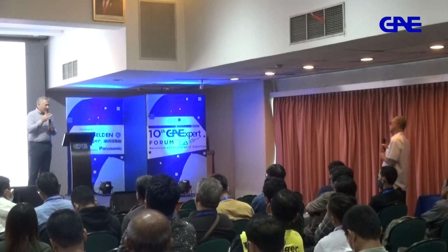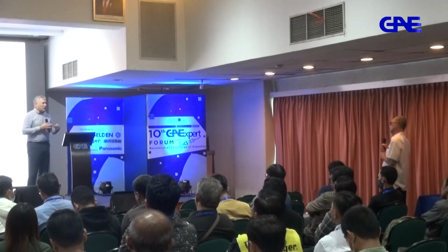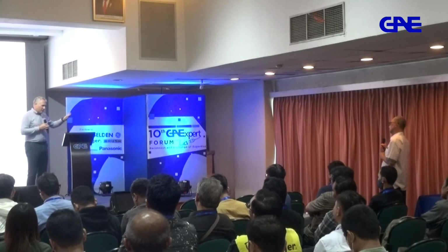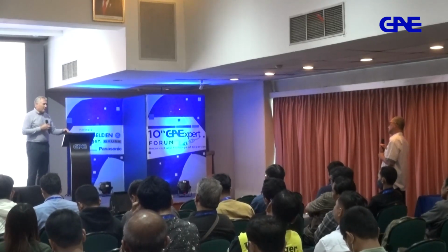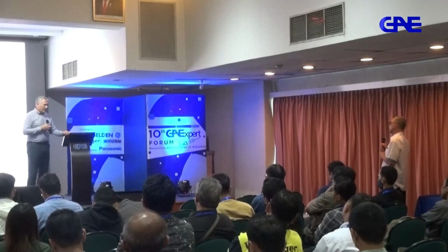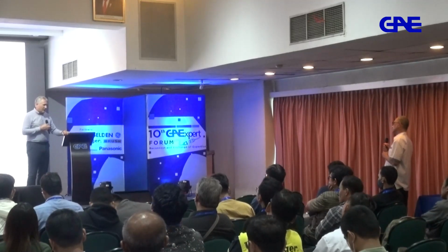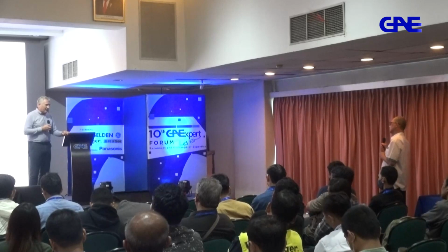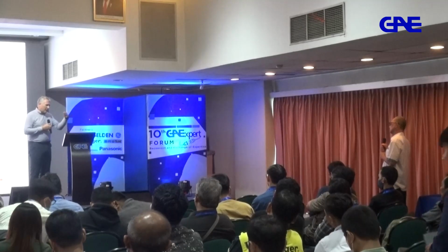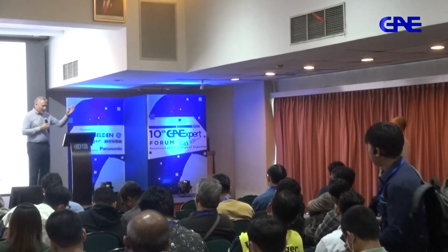That's why it's a bit tricky here, because you need to understand, first of all, the use of the equipment, subject number one. Subject number two, what's the environment in which you are testing? I was recently in a factory in Quebec, in Canada, and they had some big problems because there was an ABB factory next door, you know, the split Hitachi ABB. I was on the Hitachi side, but next door they were developing robots. These robots had switching power supplies, and whenever they were playing around with the robots, plus the crane next door, they were inducing partial discharge.